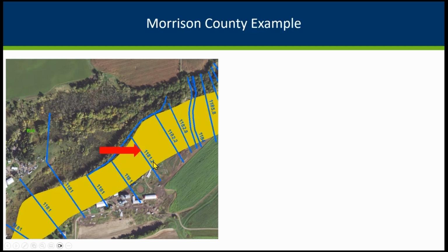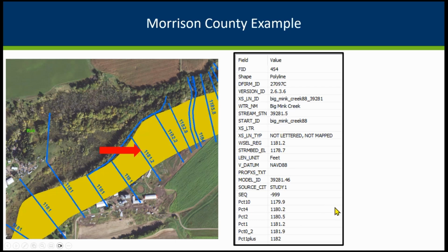And let's say I needed the 10-year. I wanted to be looking at putting in a septic system. And our state rule says, if we know the 10-year, we're supposed to be putting these things above that. So I go here in the table in my GIS, I can see the 10-year flood elevation. And we're working on getting this information into one of the layers that we've got available, and then making it a layer that could be on our lake and flood elevations online to make this a little bit more accessible.